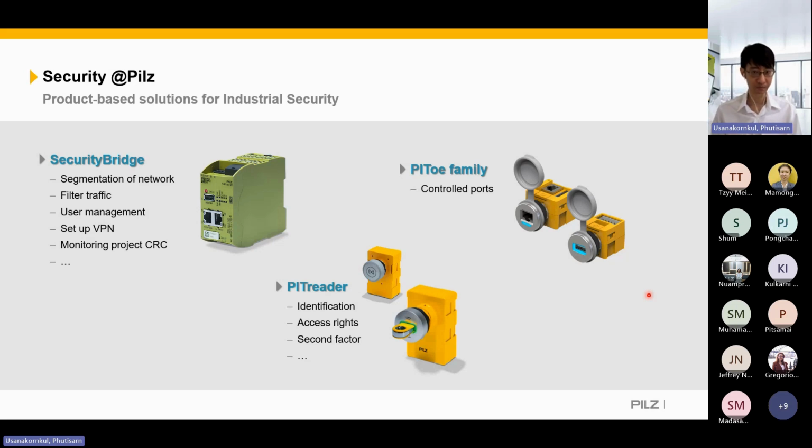If you want to reprogram or monitor something and you need this access, then this device can be used to have another protected level, instead of having Ethernet connect directly to your PLC. You connect to this device, and this device will work with other access management control that we have, which we will be talking about soon, to allow or not allow the person to access your PLC.